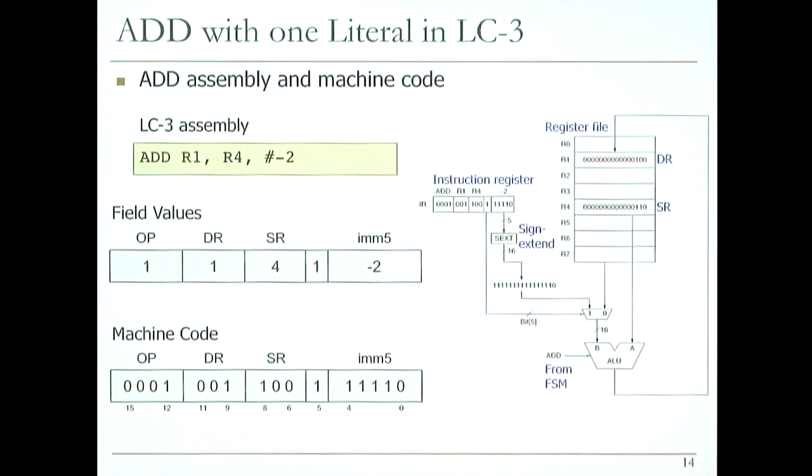This is what is called a steering bit in LC3, because this bit determines how the rest of the bits of the instruction, those bits that are after the steering bit, are interpreted by the hardware. When you look at the other ADD, the one that uses 2 source registers as operands, you will see that the value of this is 0, corresponding to this input of the multiplexer.